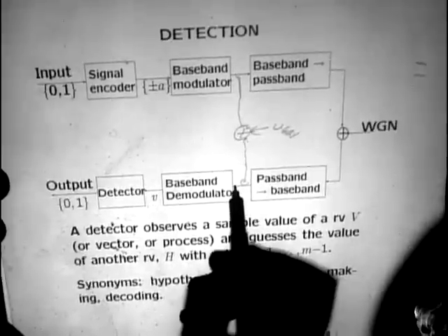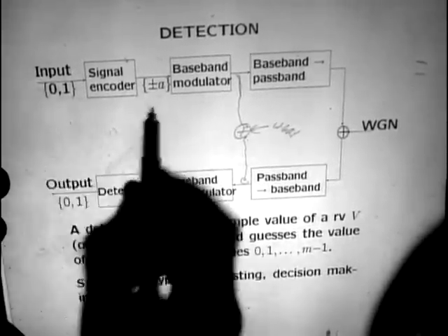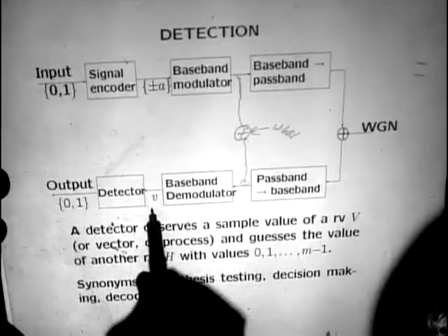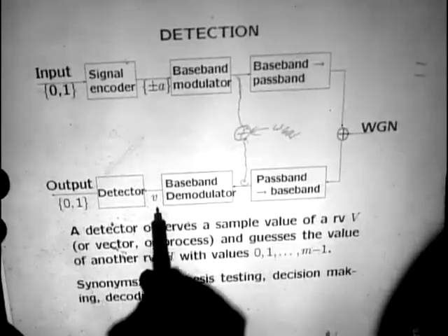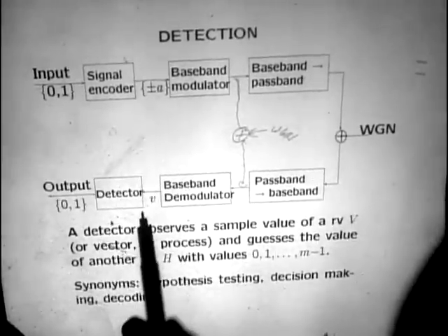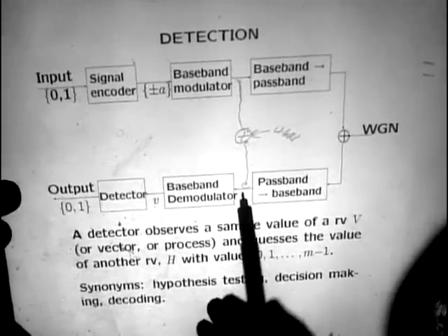The optimal detector to build now is this matched filter to this input waveform, followed by the inner product here, which is what the matched filter does for us, followed by our binary antipodal detector again. Okay? So by studying the problem at this point, we now understand what happens at this point.